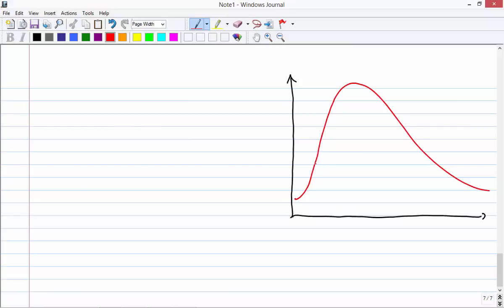These are constant pressure lines in the condenser. Here is constant pressure in the boiler, and here point 1 is subcooled, so it's a little bit lower, but the pump is still working isentropically. Point 1, point 2, and then in the boiler we are having a phase change.